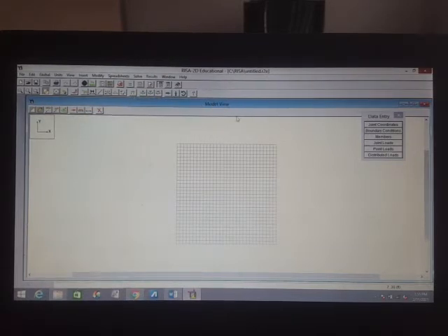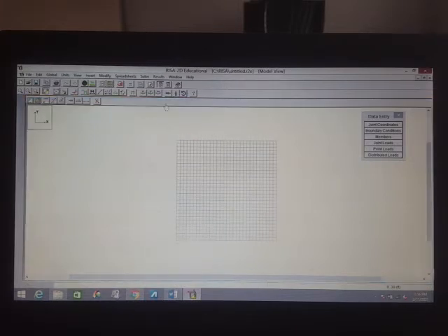Alternatively, there are also some tools here wherein if you click this, you can draw new members. It's a graphical option wherein we can draw the structure graphically. So draw members or boundary conditions, that's the supports, then apply joint loads or distributed loads, and then apply point loads or moments to members. So that's another option.